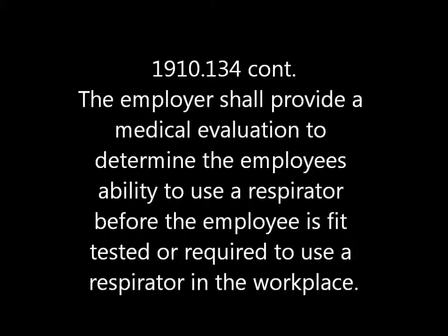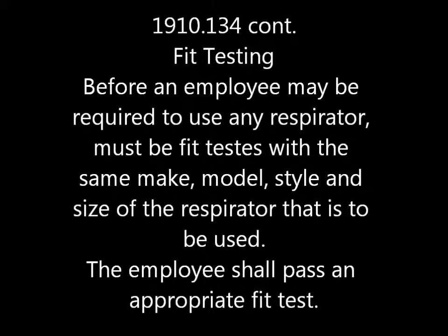The employer shall provide a medical evaluation to determine the employee's ability to use a respirator before the employee is fit tested or required to use a respirator in the workplace. Fit testing: before an employee may be required to use any respirator, they must be fit tested with the same make, model, style, and size of the respirator that is to be used. The employee shall pass an appropriate fit test.